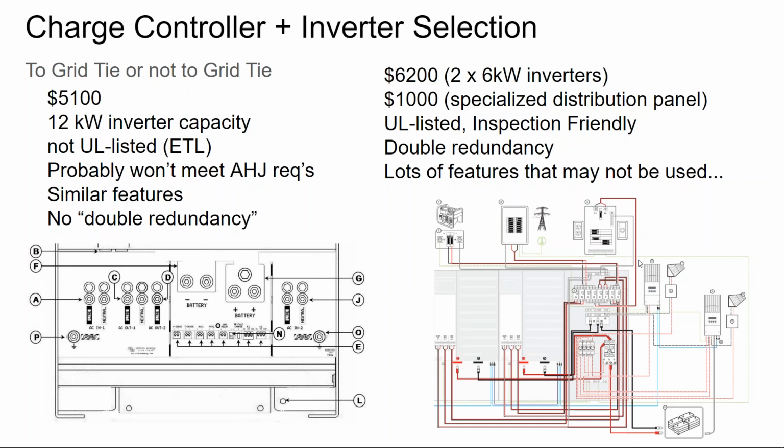And what that means is there's going to be more safety provisions built into a proper grid tie battery inverter that you just would not use for off-grid, such as your grid tie inverter needs to detect when there's a power failure from the grid and limit its outflow. That's just an issue you don't have when you go with a truly off-grid inverter.